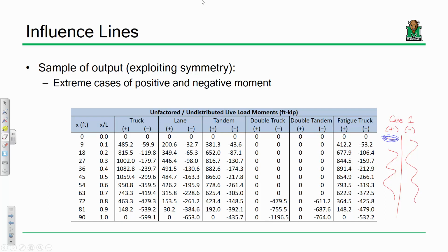Because you could take a theoretical bridge, divvy it up into 10th points, do the analysis. Then divvy it up into 100th points, do the analysis. You'll get a different answer. It won't be that much different. You see what I mean? There is a point when, in practicality, you just sort of go with it. And 10th points is generally accepted within the bridge engineering community.